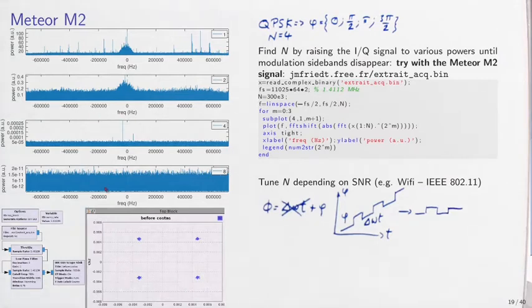In terms of constellation, you will see your constellation here with 4 possible phase states rotating as long as delta omega is left. There is a time rotation of the constellation which stops rotating when delta omega is cancelled. So how do you actually feed the whole sequence?